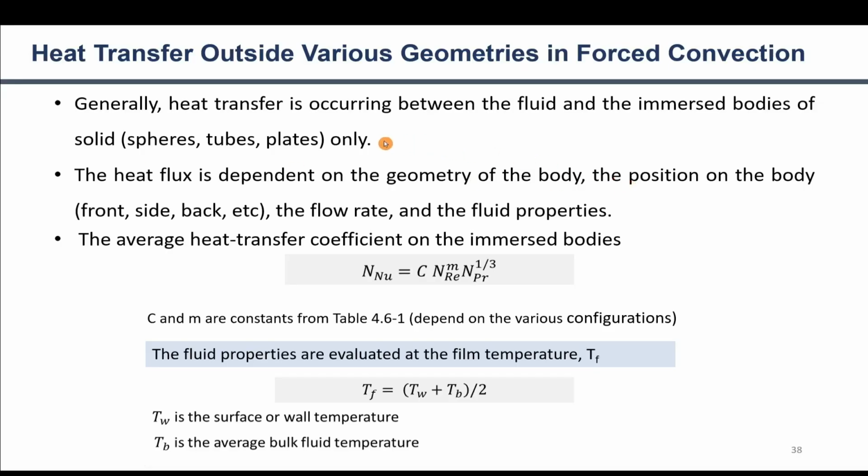In general, heat transfer occurs between the fluid and immersed bodies such as solid spheres, tubes, and plates. The heat flux is dependent on the geometry of the body, the position on the body, whether it is on the front, the side, or the back, the flow rate, and also the fluid properties.